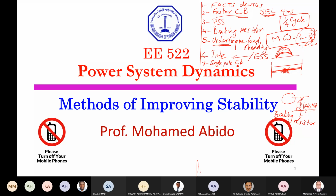Here in Saudi Arabia, we have single pole circuit breakers at the EHV side for 230 kV and 380 kV. It could be done with certain modification to have single pole tripping since most single phase faults are just temporary, and when they break the single pole and auto close it again, the fault will be cleared. So it can be done.